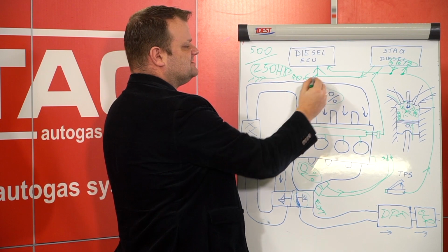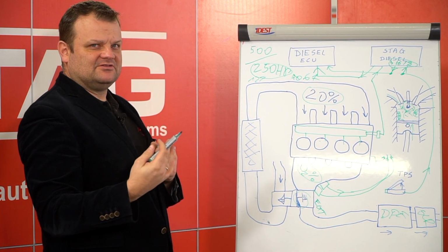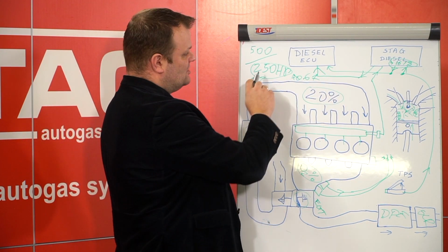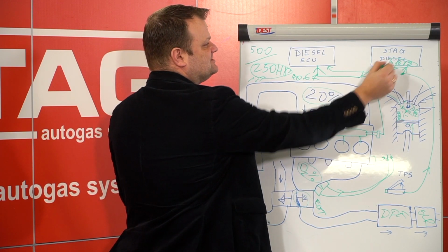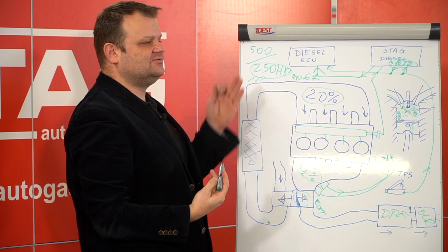67 per one injector. It's too high because it will be on the limit. On the limit, what does it mean? The injector, right? We should use, in this case, 250, we should use STAG Diesel 6 and choose 6 injectors with enough flow to handle 250 horsepower.